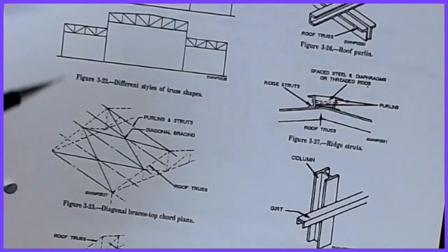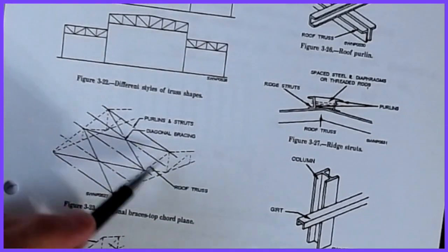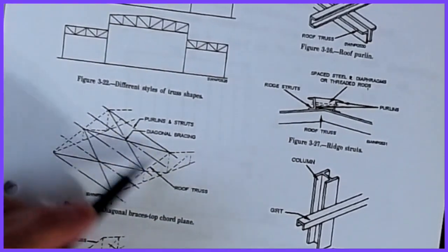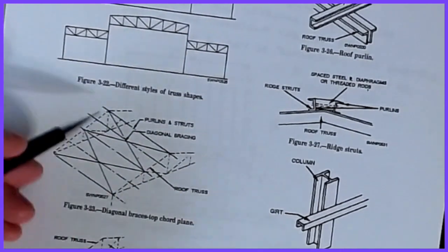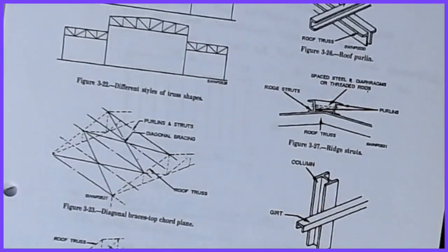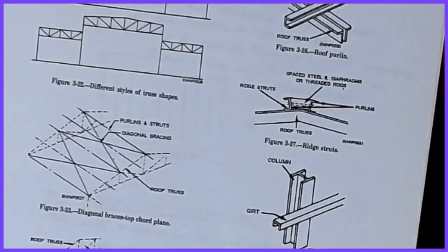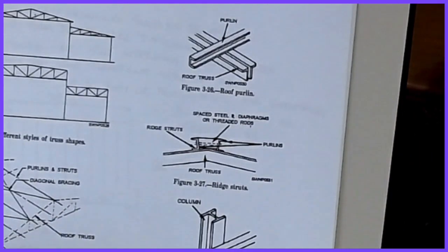And then you can kind of see some of the struts and the ties that are happening between the truss systems. So if these aren't too far apart, then a purlin would run from here to here, and then you have some sort of diagonal bracing, which helps lock the whole thing together to keep one truss from moving relative to the other. So there is some lateral framing that we haven't talked about, and when we get to design classes, we'll do more with that. And so that's the basic idea.